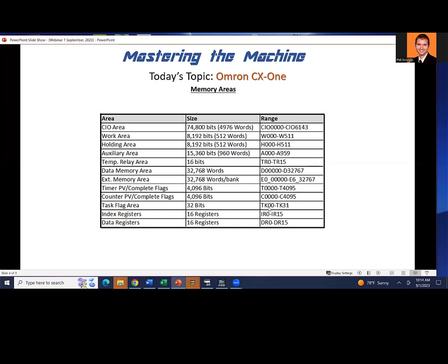These are telling you which task is running. So the tasks are kind of treated like programs are in Allen Bradley and Siemens, or routines or networks or whatever you want to call them. It's a little different organization there. And then they divide the tasks up. They're more like programs, I guess you'd call them in Allen Bradley. And they divide them up into something called sections, which are probably closer to what you might know as routines.